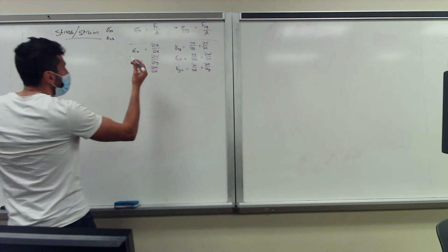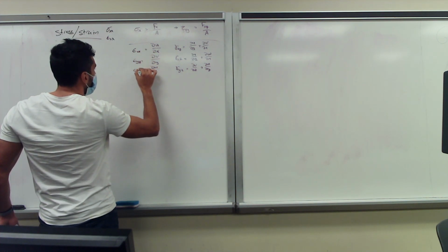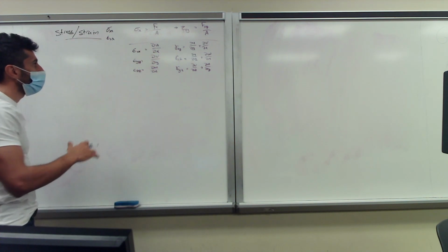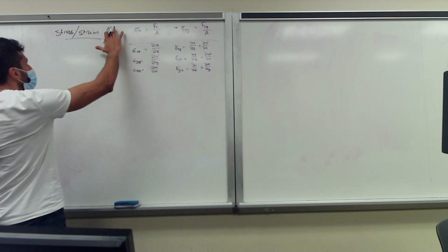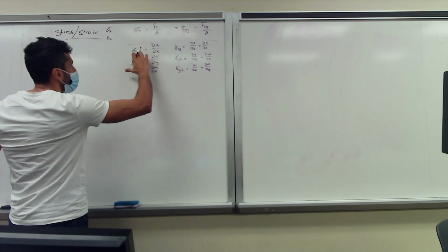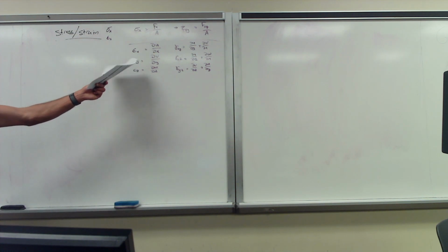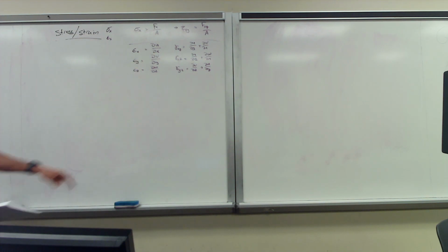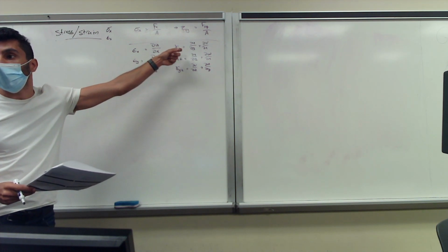So if you were 100% correct, this should be sigma xx, sigma yy, sigma zz, or epsilon xx, epsilon yy, epsilon zz. But since we're all lazy, we basically ignore those. And that's only valid when it's direct stress or direct strain, because you cannot change the shear ones, since then information is lost about how it acts and what it acts upon.